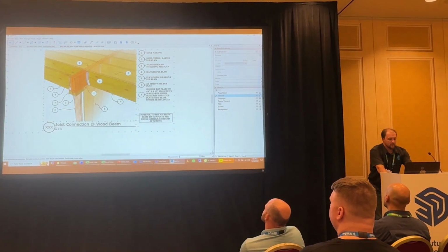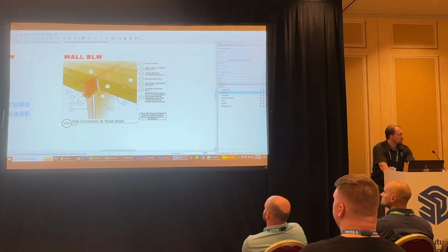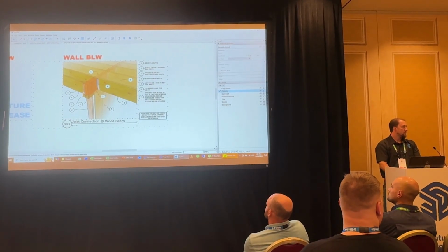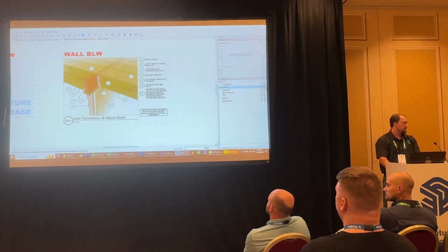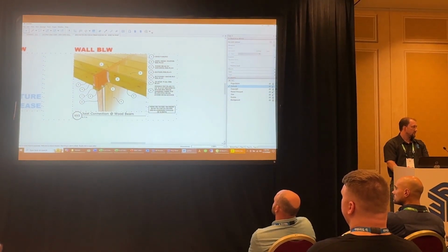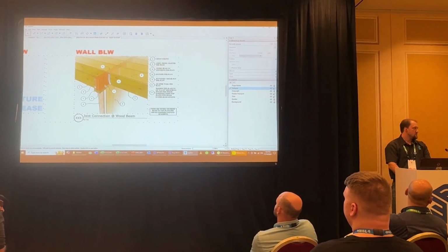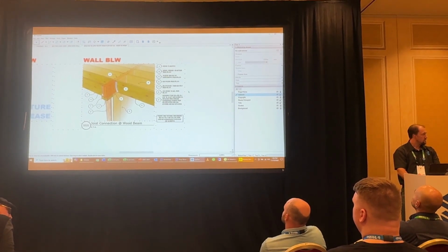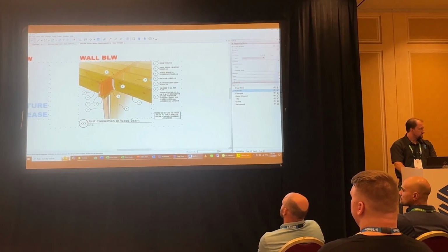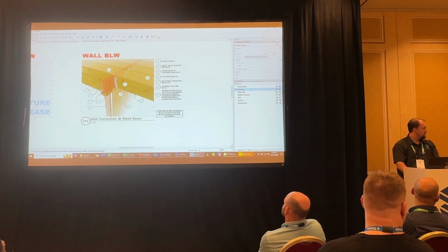What are you saying when you say keynotes? Keynotes use a numbering system, so instead of having a note with a leader to the element, it uses a substitute and then creates the list. Right now with SketchUp and AutoText, you can embed whatever you want your note to be in a component or group, and you can use AutoText with your leader to identify it, so you don't have to type it in there. Oh yeah. What we did was we standardized.